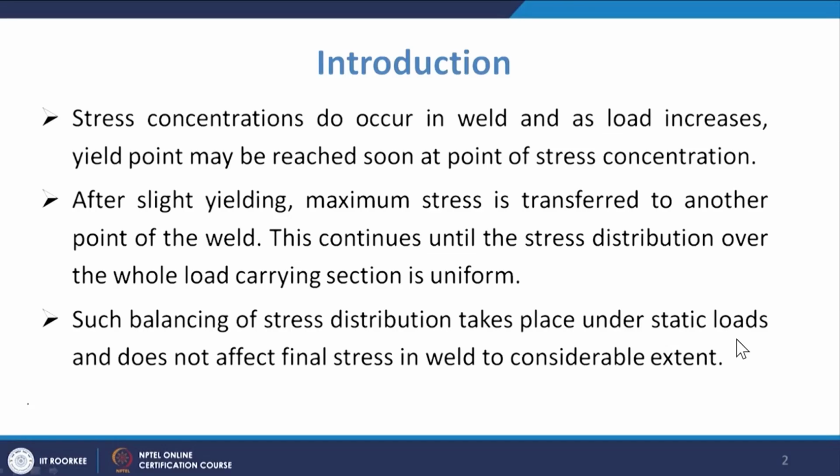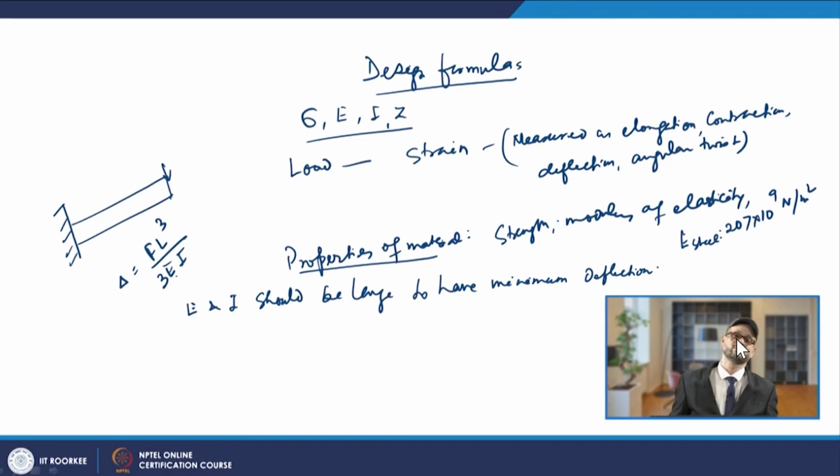This continues until the stress distribution over the whole load carrying section is uniform. Such balancing of the stress distribution takes place under static loads and does not affect the final stress in the weld to a considerable extent.